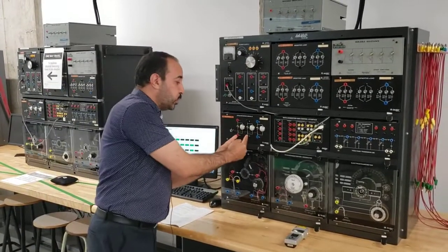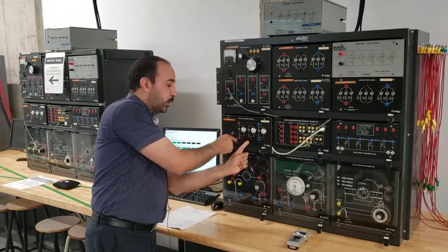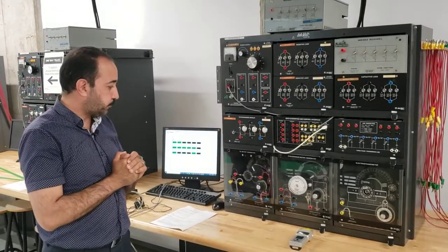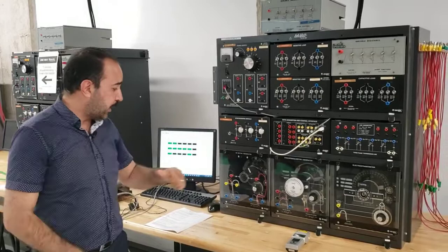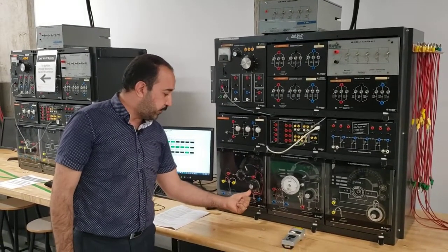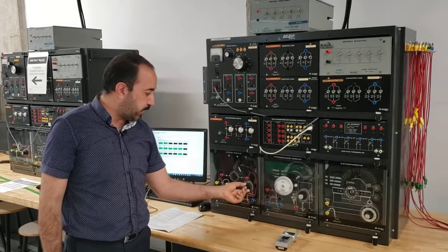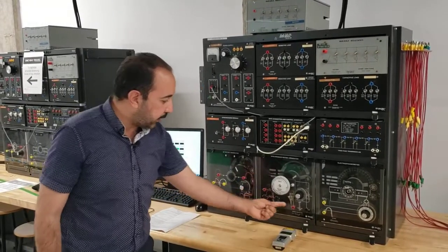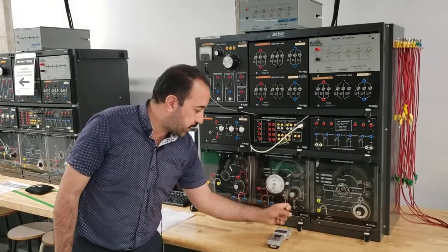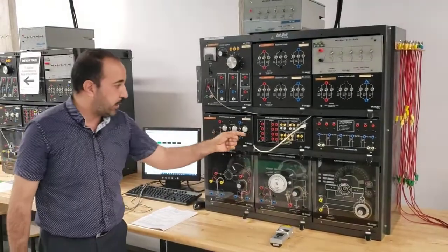So what I'm going to do is switch between two of these slot connections. So I have three components: changing the frequency to be adjusted to the grid depending on the field adjustment for the DC motor; adjusting the voltage by adjusting the field of the synchronous generator; and checking these lamps.